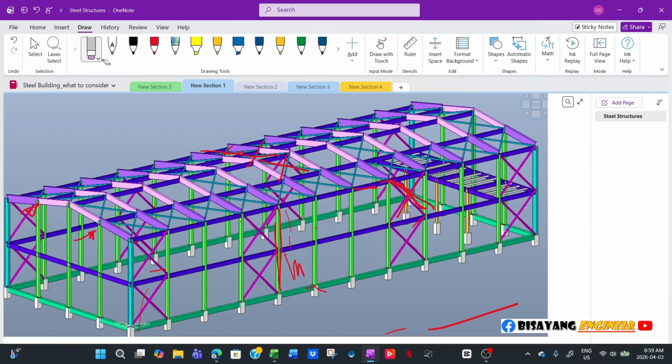So in that case, I have an option how to apply all my loads. But if you do the proper design, if you're the one designing the superstructure, then you have to consider all of this. Like, do I need this extra diagonal bracing here? Because you have to understand what that's for. Like I said, for example, this frame here, this blue one. I know that it is transferring the load like a strut, but you have to consider that there are also four lanes that run along this direction, and it can potentially carry all those compression forces.